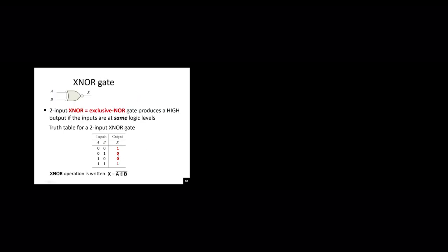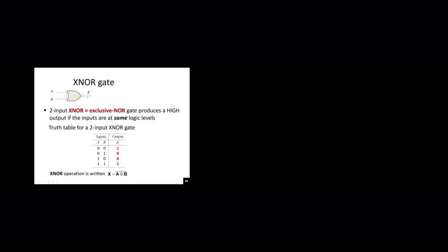And you'll see here that you can write this shorthand notation in a circuit diagram for OR followed by NOT. You can sort of squish them together and get rid of the triangle part and just have the dot at the output of the OR, and that represents a NOR gate. Same thing for an AND and same thing for an XNOR. So you actually have to look pretty carefully when you're drawing digital circuits in a circuit diagram. These little circles everywhere change everything, so you need to watch out for them.